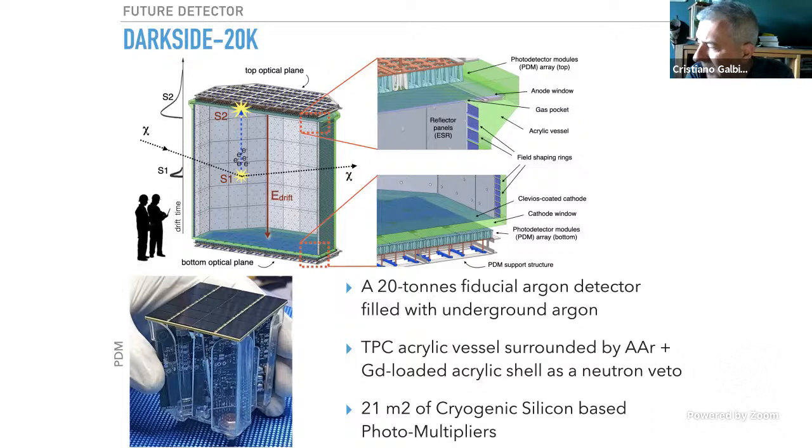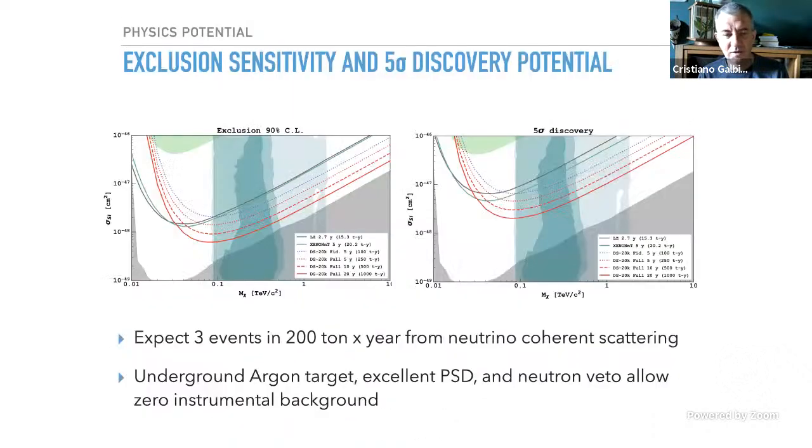When we started this development 6 years ago, the possibility of assembling a photodetector of silicon PMs over 5 by 5 millimeters seemed to be outrageous, okay? Because these devices have a very huge capacitance, and the noise is driven by their capacitance. And it seemed difficult to go beyond 5 by 5 millimeters or 1 by 1 centimeter. Now, at this moment, we have not only mastered the 5 by 5 centimeters, but we are moving forward in a direction where we build tiles of 10 by 10 centimeters, a very significant surface.